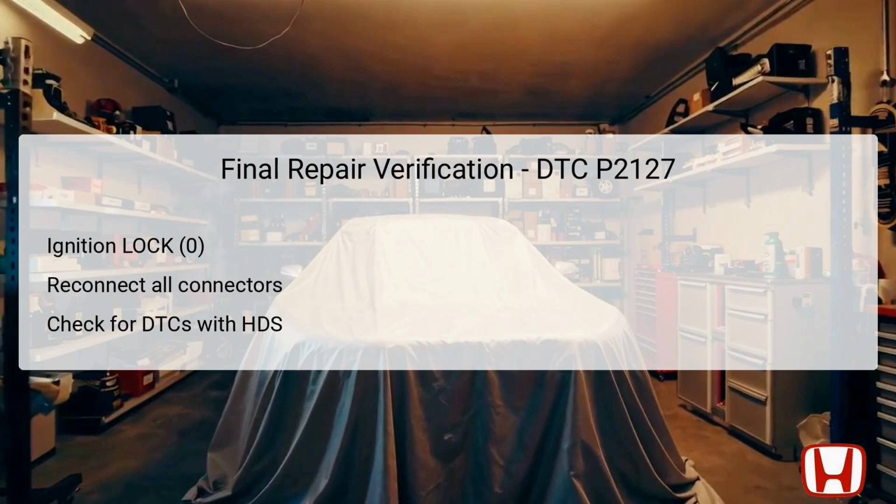If DTC P2127 reappears, investigate potential loose terminals or poor connections between the APP sensor and the ECM once more. If no DTCs are present, troubleshooting is considered complete.